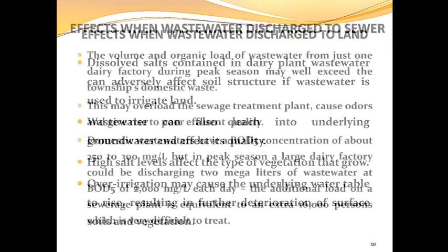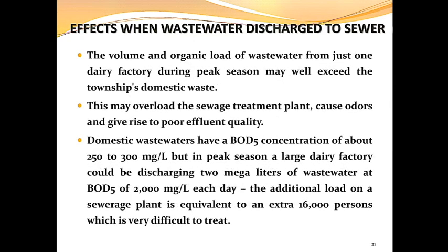These are the various effects caused by discharge of dairy wastewater to land and irrigation. What are the effects of wastewater when discharged into the sewer? The volume and organic load of wastewater from just one dairy factory during peak season may well exceed the township's domestic waste. This may overload the sewage treatment plant, cause odor, and give rise to poor effluent quality. Domestic wastewater has a BOD5 concentration of about 250 to 300 mg per liter, but in peak season a large dairy factory could discharge up to 2000 mg per liter per day. The additional load on a sewage plant is equivalent to an extra 16,000 persons, which may be very difficult to treat.